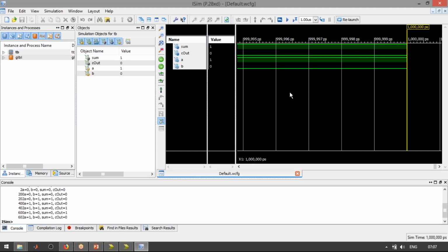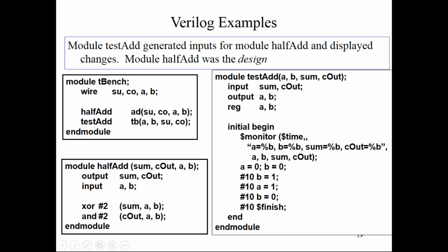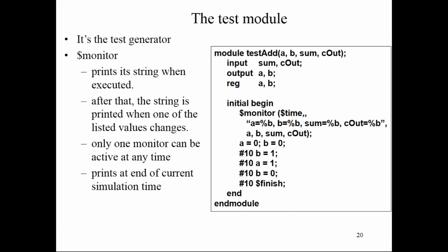Because rather than checking the waveforms, we can easily understand what input and output we got. So that's why we are preferring this monitor signal. In this way, we are verifying the functionality through test bench simulation. So this is the purpose of monitor signal.